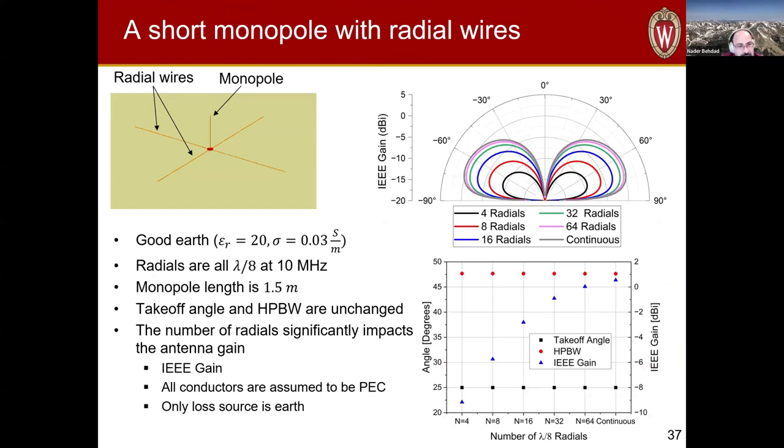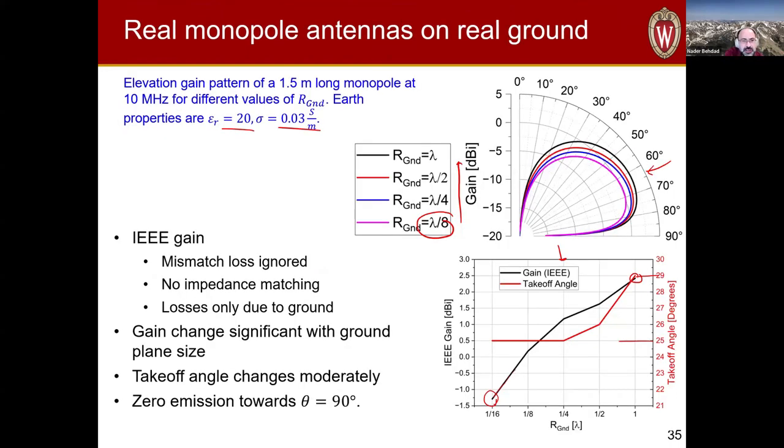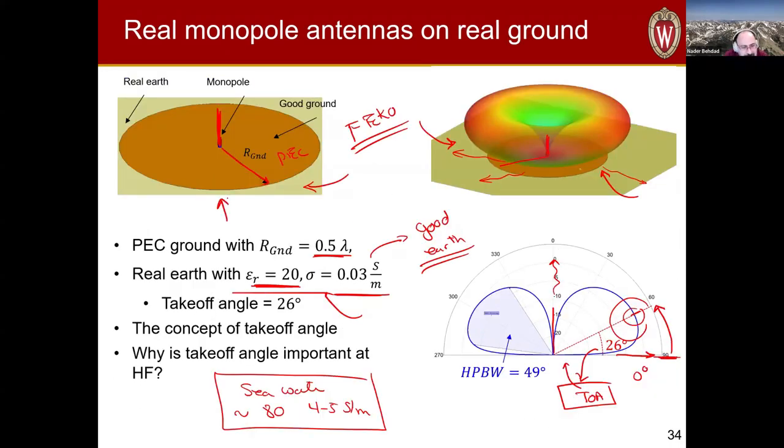Now, the other thing that we need to think about is that even the picture that I'm showing here, this one, is more realistic, but even this one is not practical in many applications. The reason is that it is pretty hard to have an actual, continuous ground plane with, let's say, a diameter of 30 meters or 15 meters or so to mount your antennas. These are physically large structures. So let's say you want to set up an HF antenna, and you have to treat a significant part of the ground in the vicinity to get anything that resembles what we are simulating.